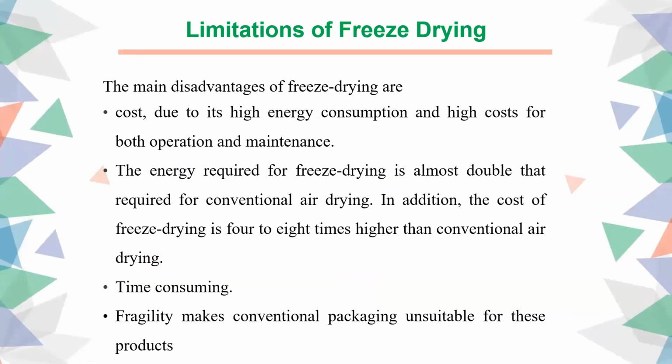Now, limitations of freeze drying. The main disadvantages of freeze drying are caused by its high energy consumption and high cost for both operation and maintenance. The energy required for freeze drying is almost double that required for conventional air drying. In addition, the cost of freeze drying is 4 to 8 times higher than conventional air drying. It is time consuming, and the fragility makes conventional packaging unsuitable for these products, so it requires special packaging units for protection during handling, packaging, or transportation.